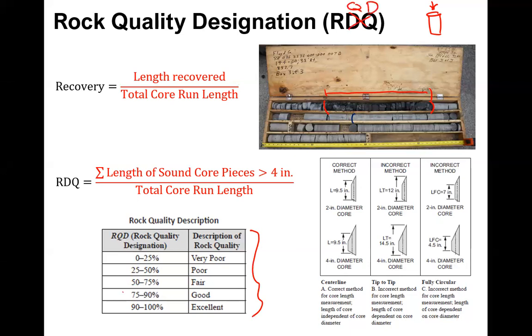So in Florida, we pretty much will never have excellent to good rock quality unless you're really deep, because the limestone bedrock that we have crumbles a lot during this process. It's not like a solid chunk like you would get with granite. Up north, in the Panhandle of Florida and closer to Georgia, you get a higher rock quality designation. But most of the time in South Florida, the peninsula, you'll get low quality rock. But that's good because that gives us our aquifer and all that fun stuff. So it's a give and take.